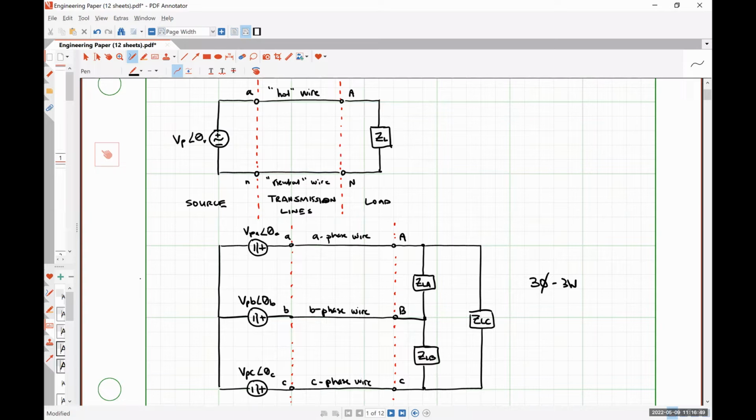There are lots of different reasons to do this. Some are to just prevent wear and tear on the startup of an electric machine. Effectively, when an electric machine starts to rotate, because the rotor is in what you would call a locked position, all of the internal inductances look like a short circuit. And so you see that its starting current is very, very large, typically 6 to 10 times larger than their rated current.